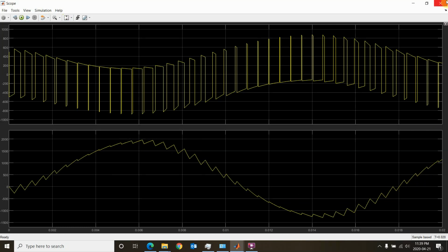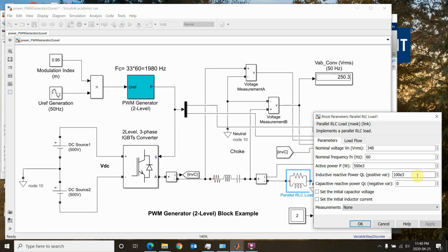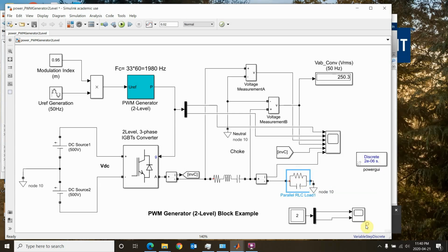The ripples are smaller, right? Because now you know that the inductor is against the change of the current, so it makes the ripples smaller. If I go back to what it was before, it should be fine.